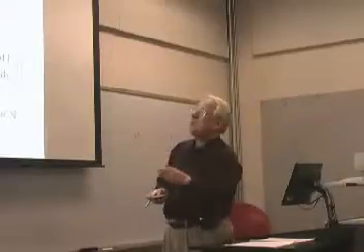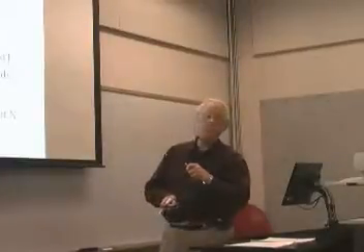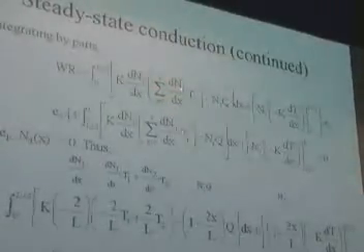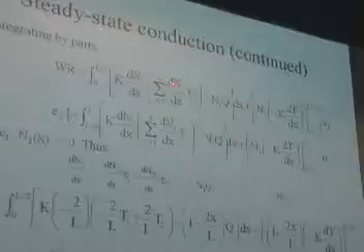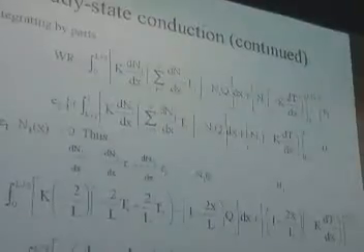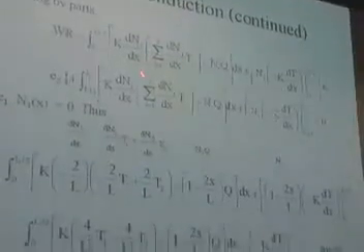So if I had this technique right here, you see I had a second derivative with respect to t. I substituted the t in terms of the N and t. Remember that expansion, N1, N2, N3? I plug it into there, so now I've got the derivatives with respect to the shape functions. So that has been weakened or reduced, you see, to a first order equation. These are a function of space, so I can solve for those right off the bat. I can do that one time. I can do it up front. I don't have to do it every time. That's what that equation looks like.